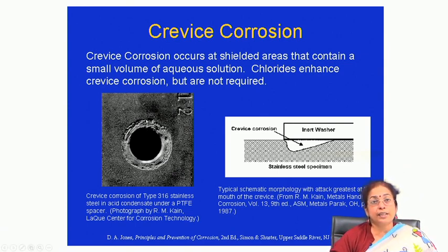So the corrosion starts, and in the crevice region, where there is electrolyte solution but the air concentration is not enough, the available air is not adequate for passive layer formation. As a result, the corrosion rate of the inner region is much higher and proceeds to a large extent as compared to the outer region, particularly because of the differential aeration cell formation.